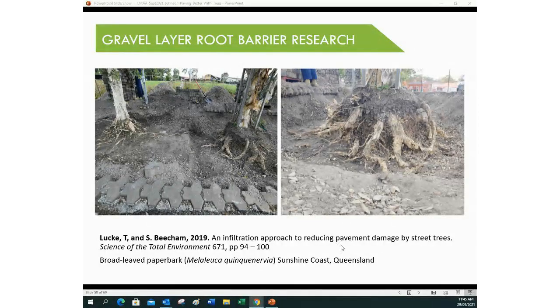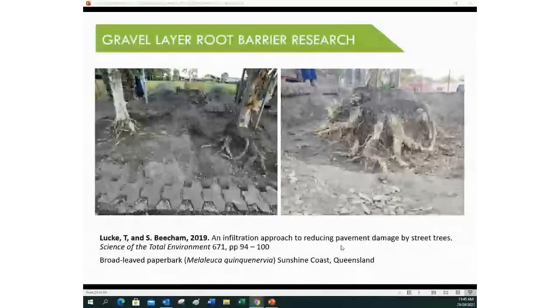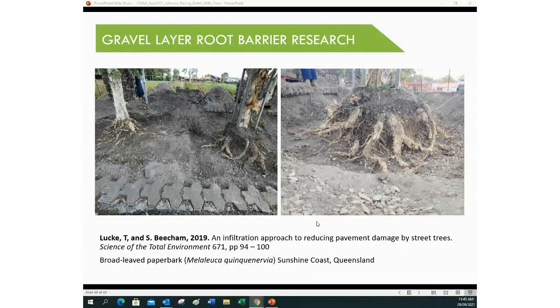As we were getting into this sort of research, we heard quite a few concerns and comments that it would be problematic putting water into reactive clay. Our research in East Parade in Kingswood is in moderately reactive clay soil. It has a shrink swell index up to about 4% per pF of soil suction. So moderate reactivity, you'd expect 60 or 70 millimetre movement over the design life of a home. Seasonal movements 30 to 50 millimetres.